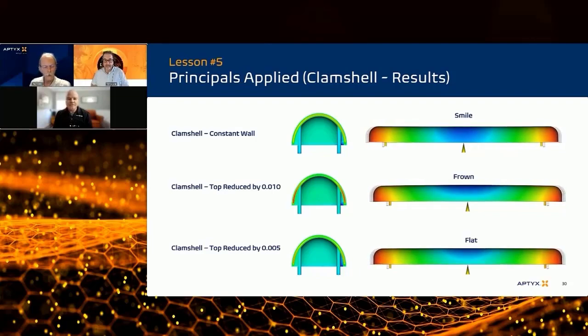Yeah, and I like to get as close as I can with the geometry changes. Often it's not a perfect prediction, so you have adjustments out there. Maybe it's not coming out exactly as planned, but you're going to be a lot closer. Then you can use temperature as one more tool in the toolbox for your final tuning. You never want to be at one extreme corner of a potential window, or outside the limits of the material and mold temperatures. It's not a good place to be as far as reliability. Yeah, great.